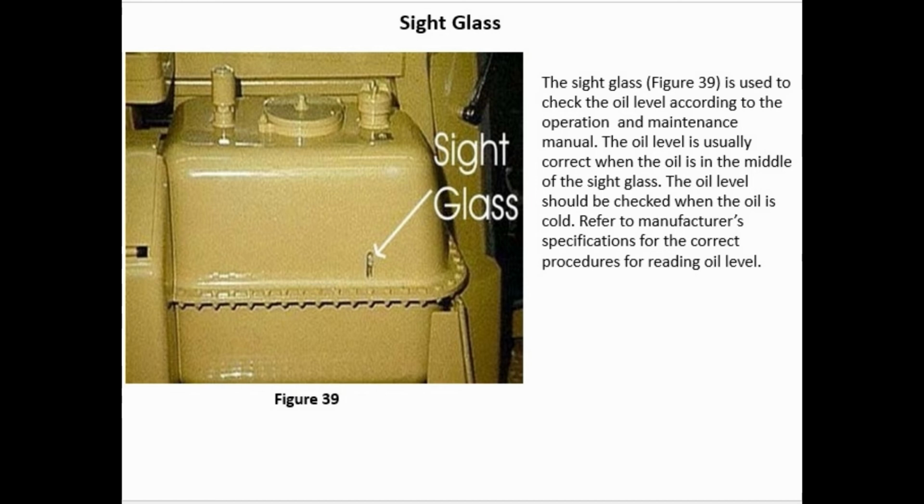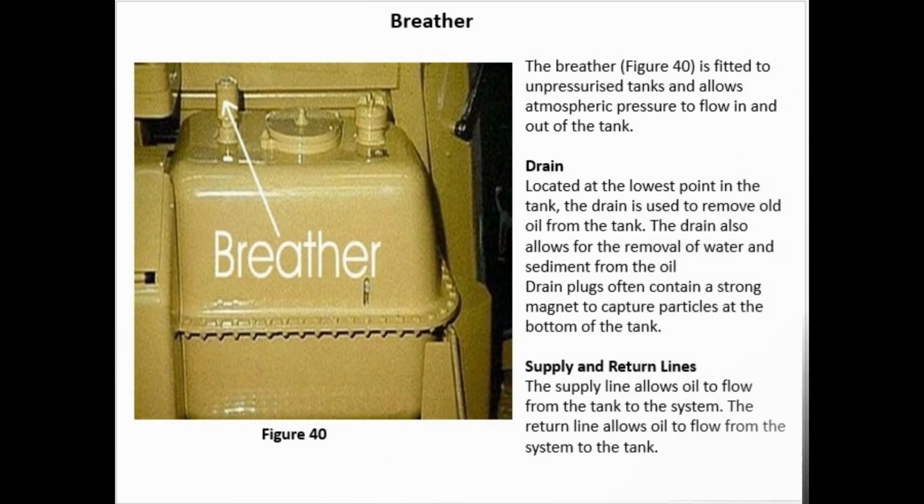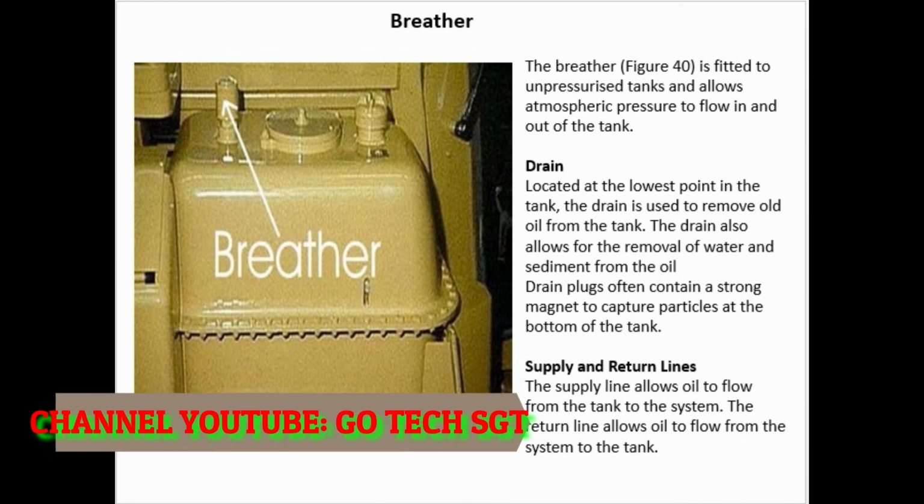The oil level should be checked when the oil is cold. Refer to manufacturer's specifications for the correct procedures for reading oil level. Breather. The breather, figure 40, is fitted to unpressurized tanks and allows atmospheric pressure to flow in and out of the tank.